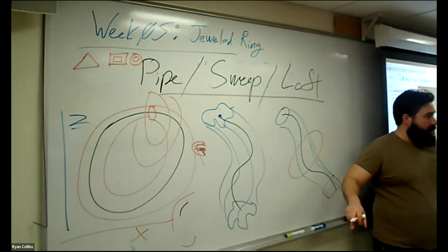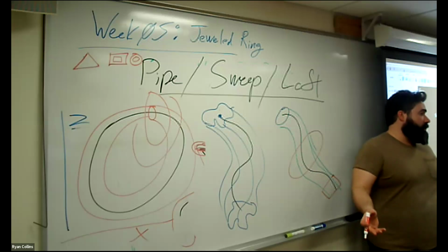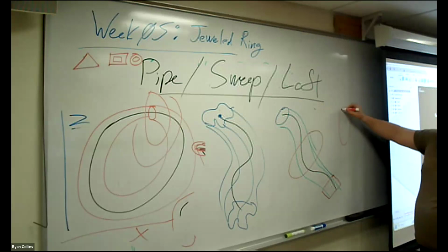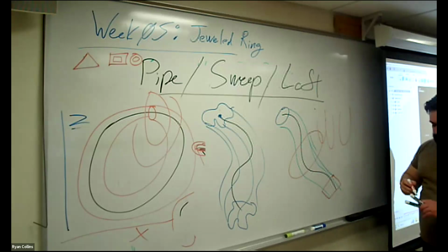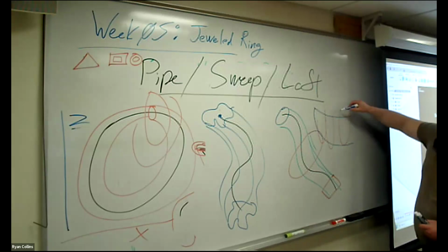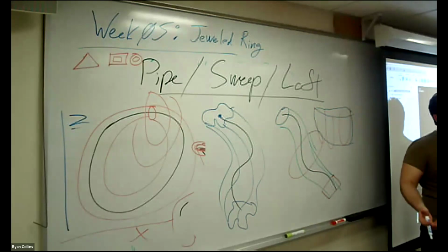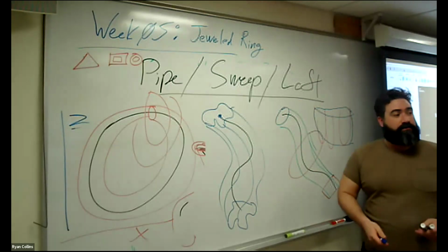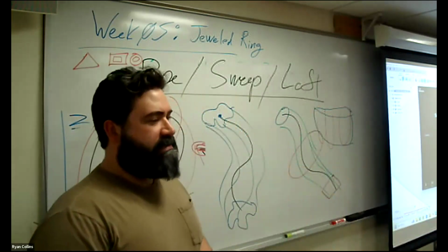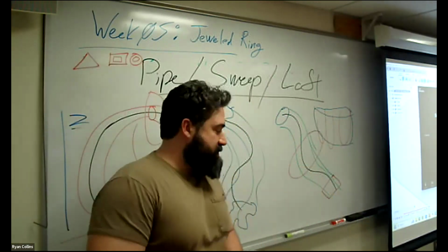Now, this is just drawing on a single line. You can do the same thing with more, and this is how, say, if you were so inclined, you'd make a boat hull. Loft is perfect for something like that because you start with, say, just a point. You end with what will be a U. You would have multiple ribs in between, and it would transition between all of those to create your boat shape. So that's how you could use these different ones. Or, of course, the same thing for, I don't know, an airplane, whatever. You get the idea of just more complex, not necessarily tubular shapes, but kind of sort of. So those are the basics of those three different tools.